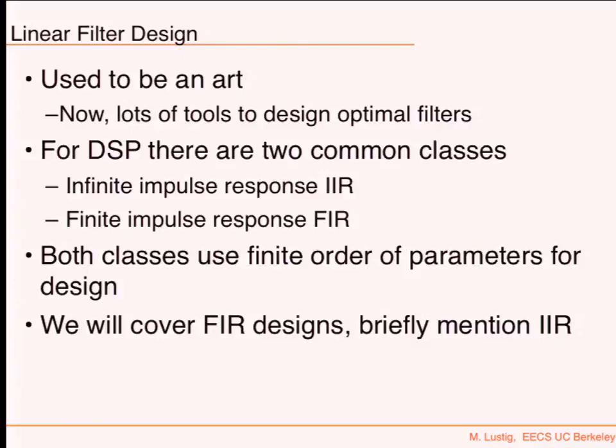Now, for DSP, there are two common classes of filters that people use, and we're talking about linear filters, so not nonlinear filters. Not adaptive. Basically, something that you can describe using a simple linear system. And then there's the infinite impulse response filters, IIRs. You did cover those in 120, so I'm not telling you something new. And there's the finite impulse response filters, FIRs.